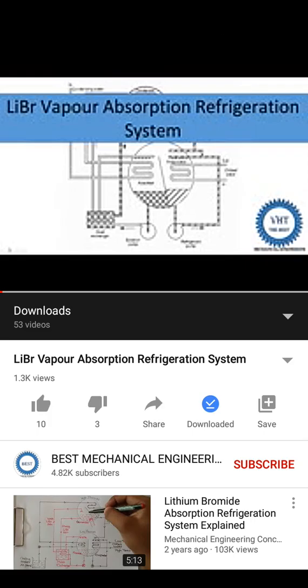In this video, I teach you the lithium bromide vapor absorption refrigeration system: what is the absorber, what is the refrigerant, and its chemical. So, in the lithium bromide system, this lithium bromide is used as an absorber, as its name suggests. Lithium bromide is used as the absorber and water is used as the refrigerant.